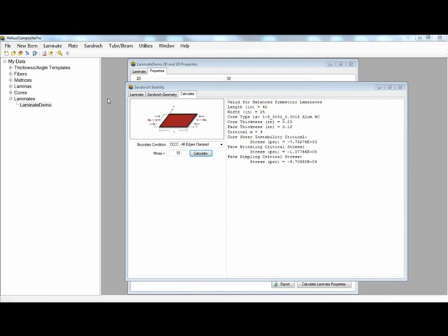Another common example when conducting a finite element analysis of composite structures is how to determine the buckling loads of, let's say, a composite column that's used to reinforce a composite structure that's being loaded in compression. In this case, unless we run a geometrically nonlinear analysis in our finite element solver, we really don't have a good understanding of the buckling loads when applied to our structure that will cause our composite columns to fail. So we can use CompositePro to get a more accurate understanding of when our composite columns will buckle.